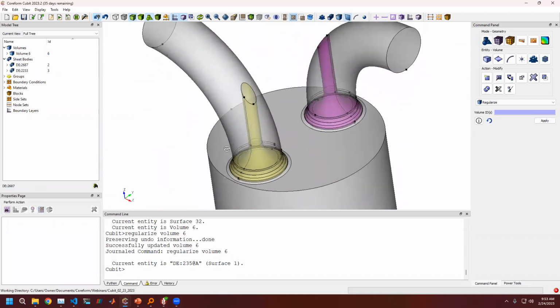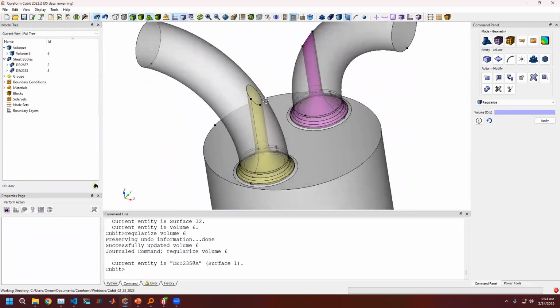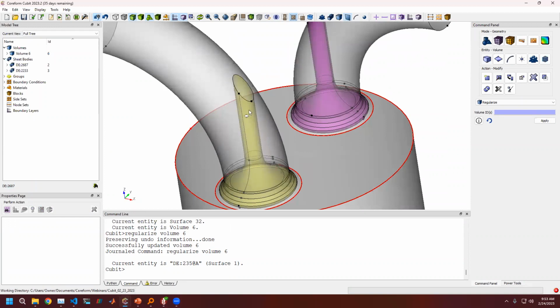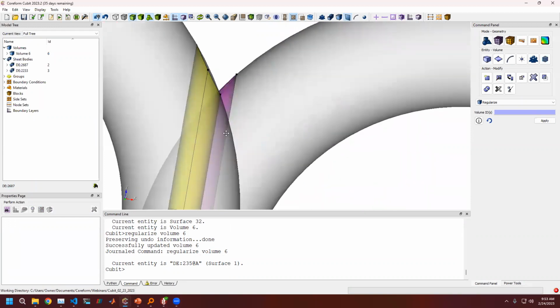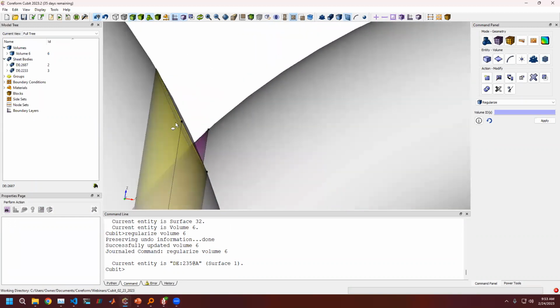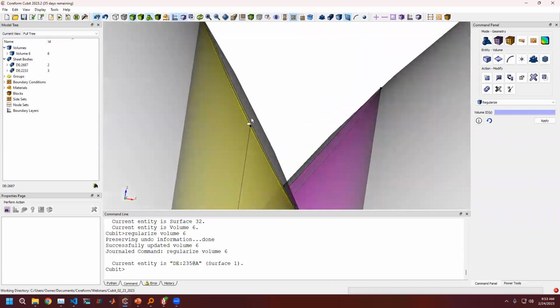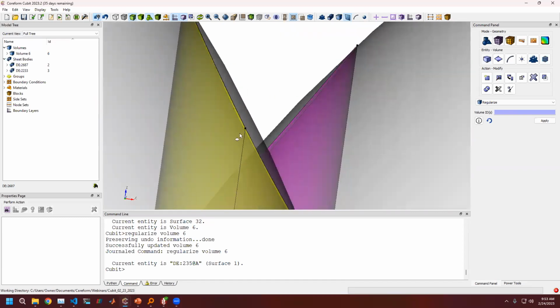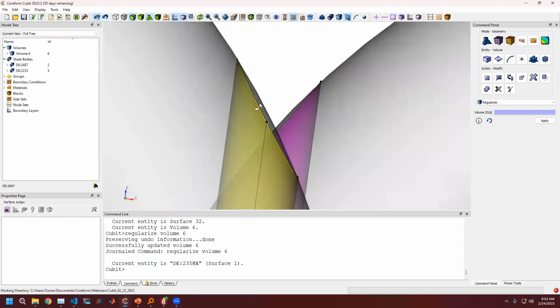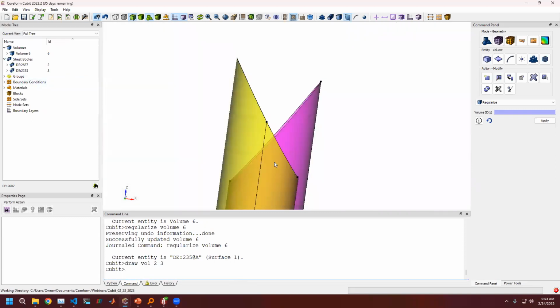So that fluid region is looking really good now. Now what I want to do is look at these valves. And if we notice, if I do a cross section through the valve, it's going to be a plane surface. It doesn't quite fit to the torus. So this is going to cause some issues here. So as a first step, let's just draw volumes 2 and 3.